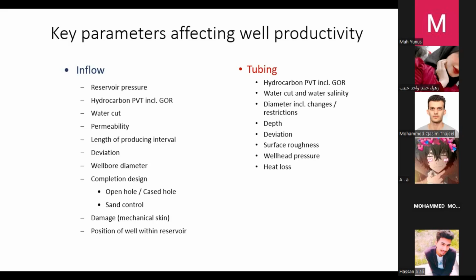You have casing in the wellbore, so that's affecting the inflow. That's affecting the KH and affecting the inflow. If we have a sand control restriction, that will give a high delta P between the reservoir pressure and bottom hole flowing pressure. That will affect the inflow.